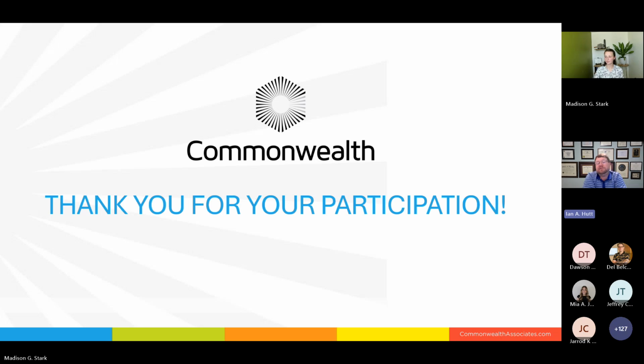So you can always conservatively say, rate your breakers at the momentary value, understanding you may be overbuilding a little bit. But when you have a higher X/R ratio, you'll have to do some complex math to understand where you're really going to be. We've done that with a few projects in the past, so it's something to keep awareness of. If your X/R ratios are high, you'll see that the short circuit envelope will collapse slower and you may need higher rated equipment.